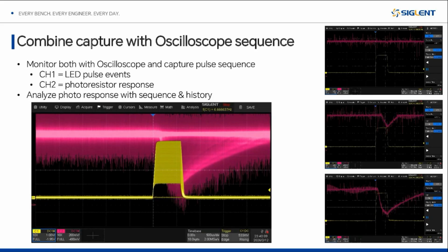Right? So this kind of test would be a great way to do late stage design work or failure analysis on these links. Maybe you've got illumination leakage in other places. Maybe you've got electrical noise coming in and it's causing you some grief. But being able to look directly at these measurements, both with spot measurements of high accuracy with the source measure unit, and simultaneously looking at the timing, impact, and accuracy of each cycle with an oscilloscope.